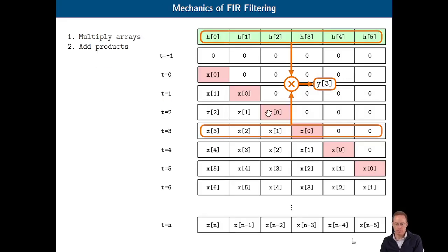Now, before we go any further, I want you to just think about what the data array would hold at time n. Previous to this, we would shift over all of this data, and we would insert this new sample x of n. Now just look at this for one moment. Notice that the indexes decrease as we move from left to right. So here we have xn, which is the current input, xn minus 1, that was the input that we received the last time around, xn minus 2, xn minus 3, and so on. So the input signal in this example is written in time reversed order as we move from left to right.